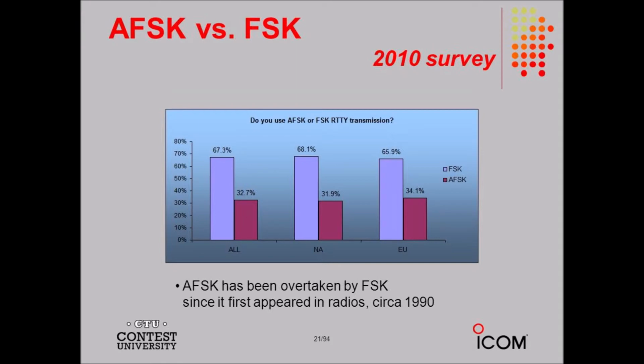The main reason why FSK or AFSK work better than on-off keying is the fact that the space signals are identified as such, rather than existing as mere gaps in the data. A sudden noise burst in an on-off keyed signal can confuse a receiver into falsely reading a space as a mark. But when the space is positively represented by its own signal, this type of error happens less often at any given data speed. Amplitude modulation.